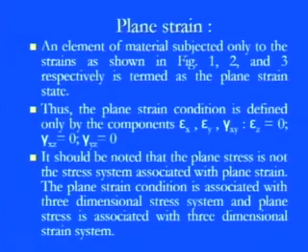So in this chapter we discussed what strains are there because of the application of load, and if we are pulling in one direction, what the corresponding changes are in the other directions. To relate those things, the Poisson ratio is an important factor, and also Young's modulus of elasticity is to be defined for the elastic region where the stress and strain are proportional to each other. And then in the last part we found that if a material is subjected to all three kinds of strains, then the strain at an inclined plane is exactly similar to the stresses at the inclined plane, and it is symmetric.